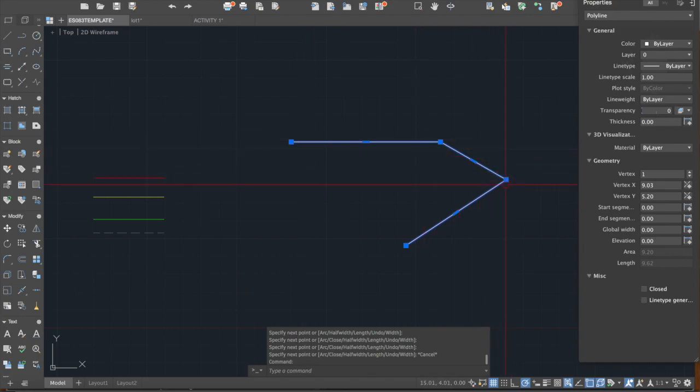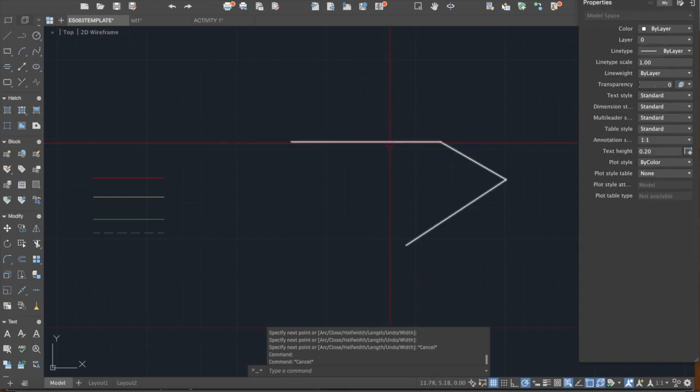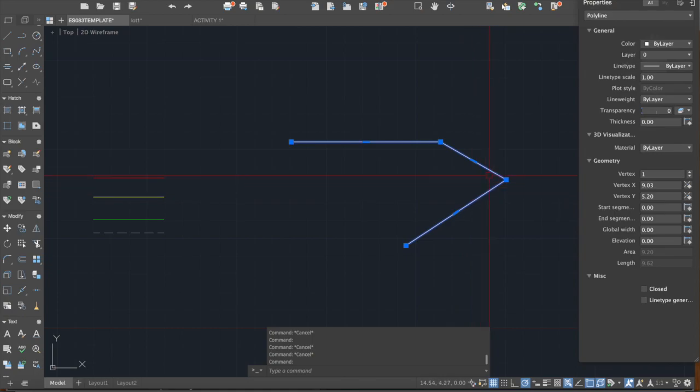So it means that we created one object. So meaning a polyline is a continuous line, different from the line command. Okay. So with that, when you select a polyline, it will highlight or select all of the lines that were included during that process.